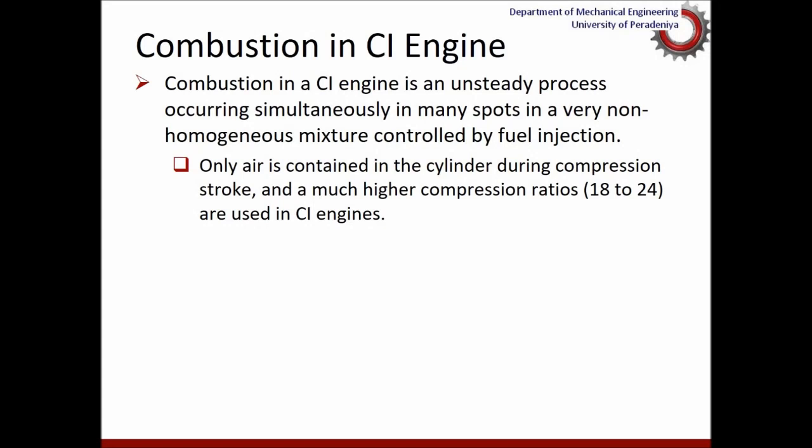So, as we discussed earlier, with diesel we can operate at very high compression ratios because the combustion duration is much shorter. Unlike in the case of premix combustion, we promote auto ignition. The diesel ignites on its own. There is no spark ignition in diesel combustion. Therefore, we could go for very high compression ratios.